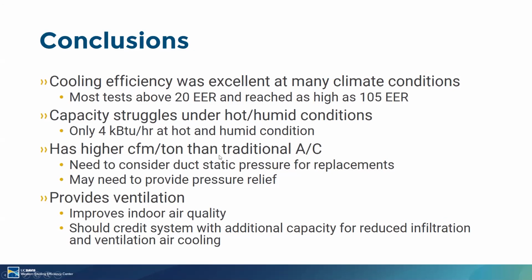Bringing in this outdoor air into the space, you have to essentially figure out how to do that. You might need some pressure relief for your building. And in a case where you're using all this outdoor air to provide cooling, it's relevant to point out that in a situation where you have good quality outdoor air most of the year, absent terrible wildfires or something like that, overall with filtering, you would expect that using a product like this for air conditioning would improve your overall indoor air quality by removing indoor contaminants.